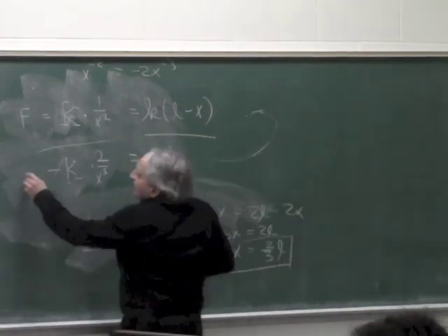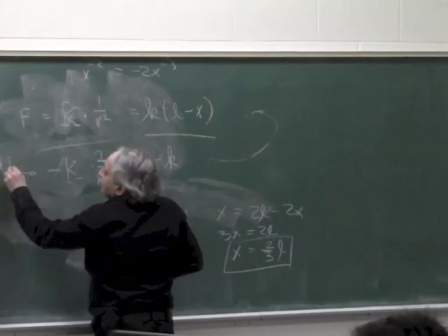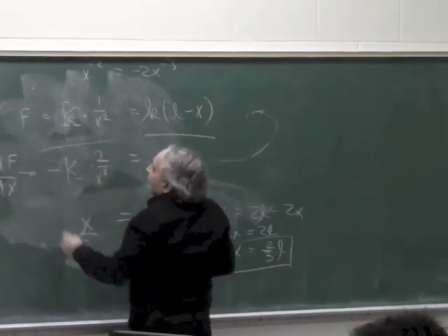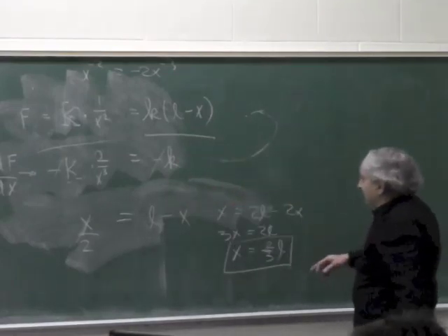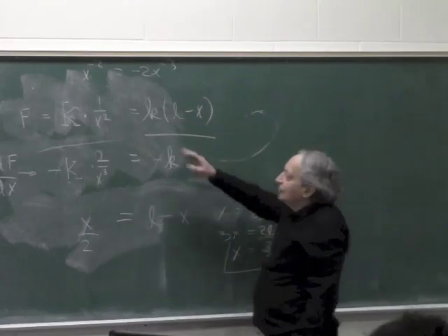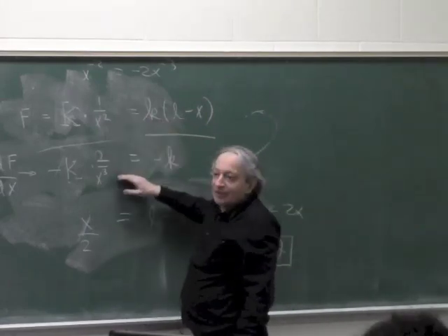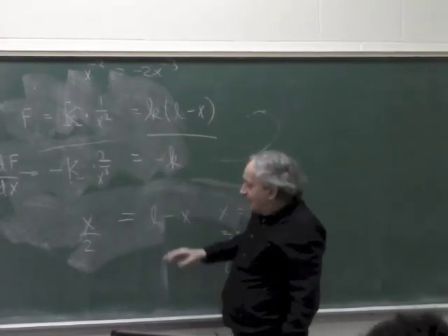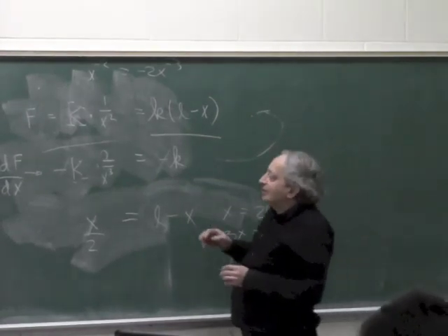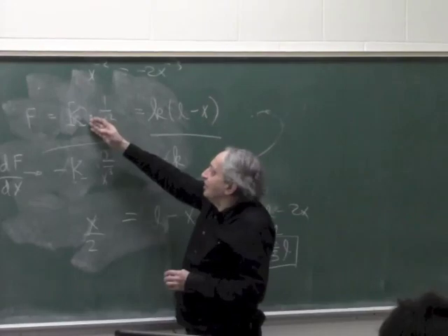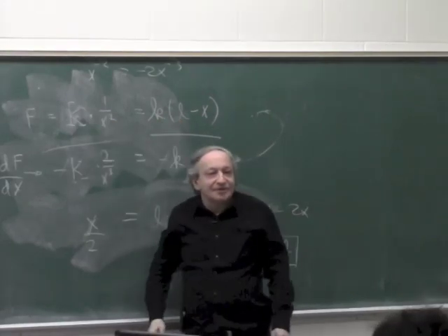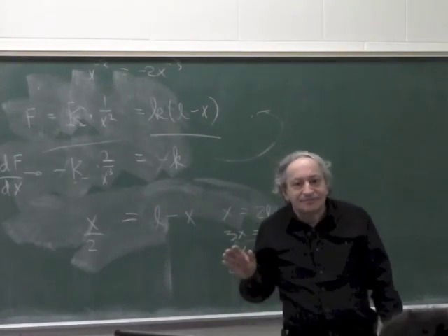So again, the bottom line is df over dx, and the top line is f. So at x equals 2/3 L, both the forces will be equal and the derivative will be equal. If I make x any smaller than 2/3 L, the derivative of this will be bigger than the derivative of this, and it will be a runaway condition, it will snap. So is this derivation clear?